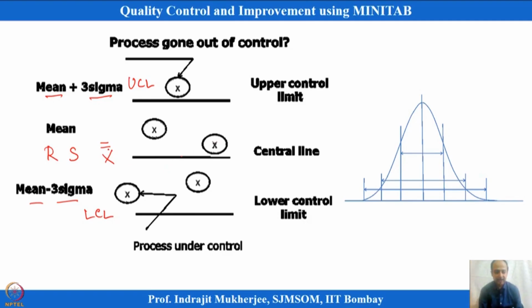So, if this is the average of the process, which may be very close to mu 0, let us assume, and s may be the estimation of sigma over here. Generally, if I draw a limit line on this side from x double bar, what is expected is that for any process at any given time point, if nothing is changing, all the observations should fall within this.